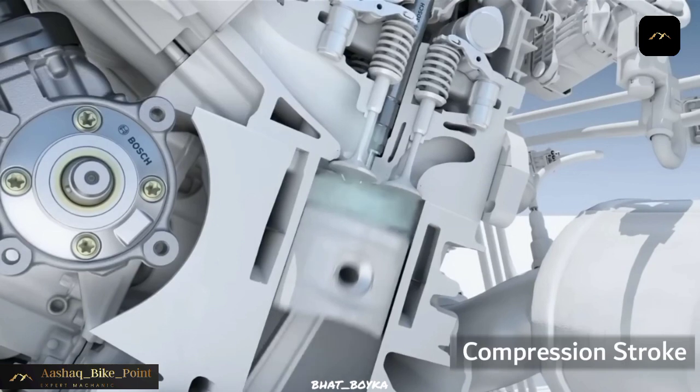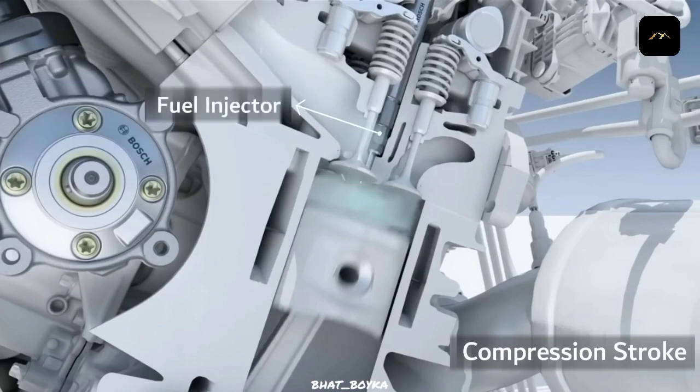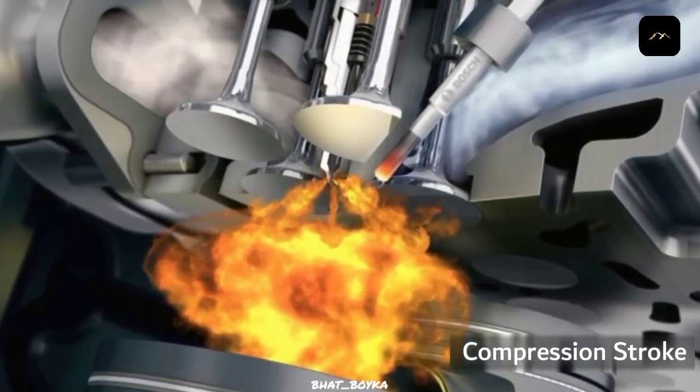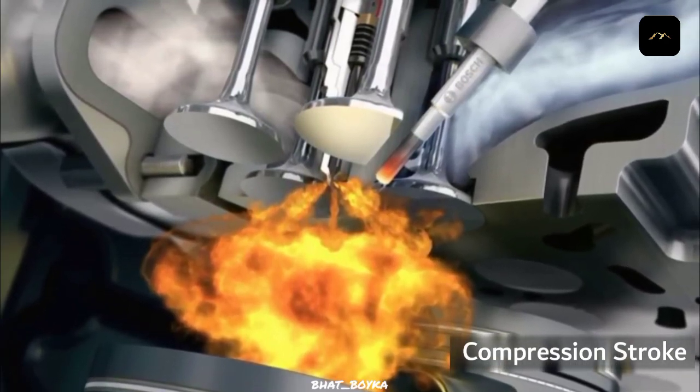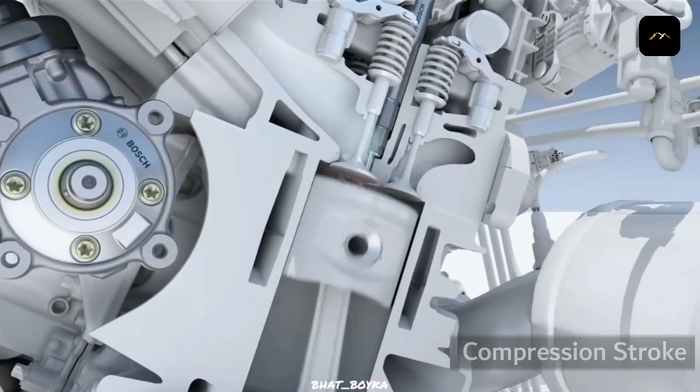Just before the piston reaches top dead center, diesel fuel is sprayed inside the cylinder. The fuel is sprayed by means of a fuel injector, at a very high pressure, overcoming the pressure of the compressed air. The fuel gets mixed up with air, which contains oxygen. Since the fuel is a hydrocarbon, the temperature of the compressed air is sufficient to initiate the combustion, and the fuel is burnt.